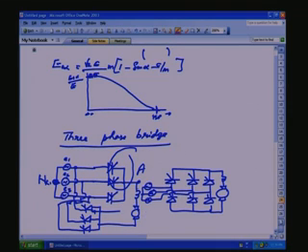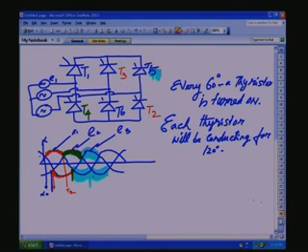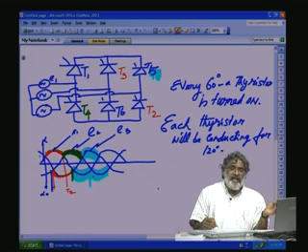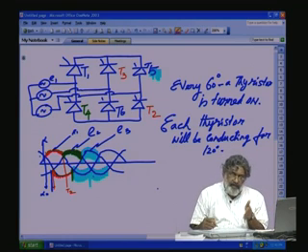So, the total voltage across, the instantaneous voltage ripple, let us see, this is B. So, VAN, that is the positive half bridge ripple, minus the negative half bridge ripple. AN minus BN, the negative is already negative, so when you subtract it will become positive again. So, AN minus BN is the net ripple content. You can find this out easily. So, the output ripple will be the positive ripple minus the negative ripple. As alpha is increased for the positive side, the corresponding alpha for the negative side should also be increased for symmetric operation.